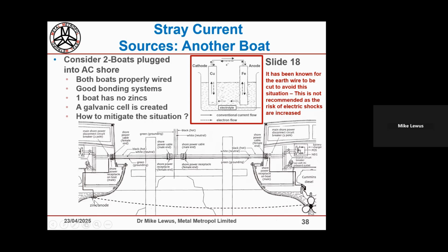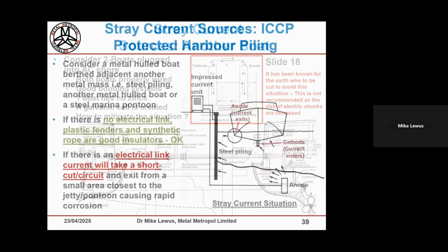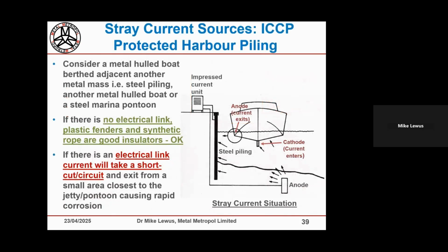The zinc anodes on one boat will also be protecting the parts on the other boat. So you've got a bigger surface area of metals connected, which means this boat's going to lose its anodes quicker. You've got to chuckle, but obviously you're not going to be chuckling if you're the owner of the boat who's diligently always replacing his anodes. There are ways around this, not least using a galvanic isolator.